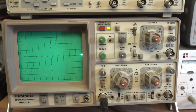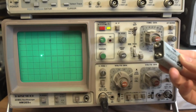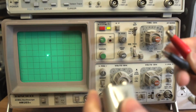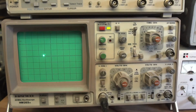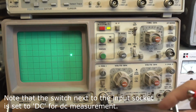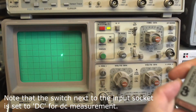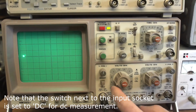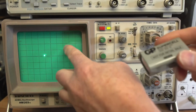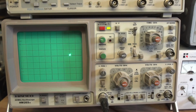And I can show that if I just use a regular 9-volt battery. So just a standard square 9-volt battery. And if we connect this 9-volt battery to the input of the scope, we should see almost 2 divisions of deflection, because that's a 9-volt battery, and it's going to take 5 volts to move it 1 square. So this is nearly 10 volts almost. So we're looking at not quite 2 squares. So let's give that a go.